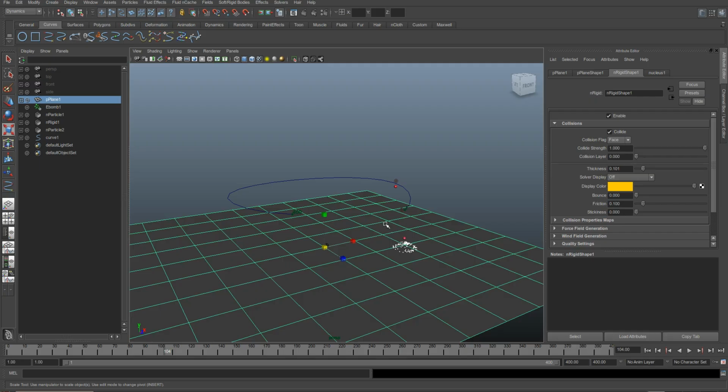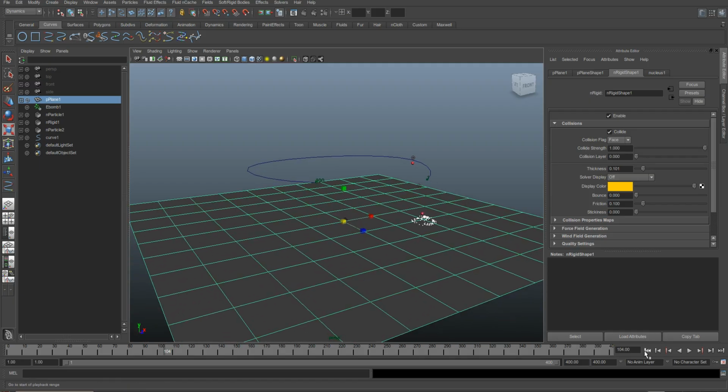Now the way we're going to get the bump map and the displacement and eventually the transparency, and we'll use transparency to mix two materials together via a Maya layered material. If you've never worked with a layered material, it just allows you to mix several different materials together in Maya, several different shaders together. We'll cover it in this particular lesson. So the way we're going to get those bump, transparency and displacement maps is by using a 3D fluid texture. So let's go ahead and create one of those.